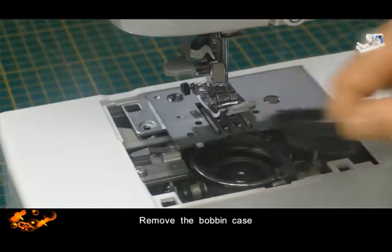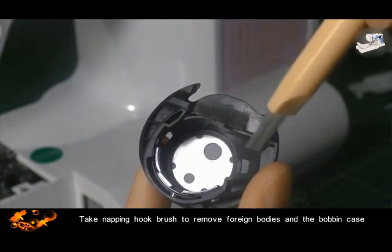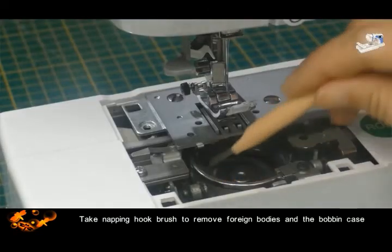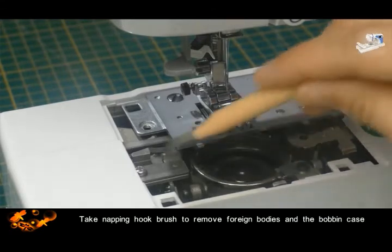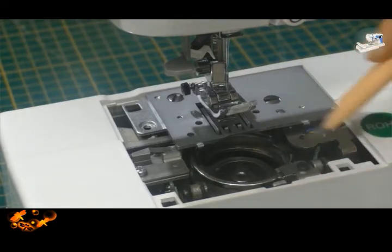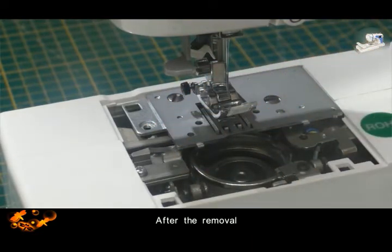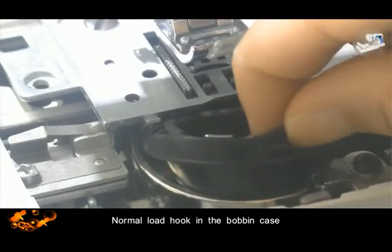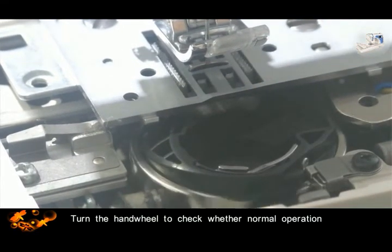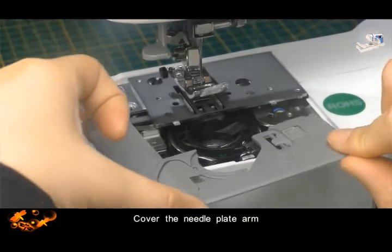Remove the bobbin case. Take the hook brush to remove foreign bodies from the hook and the bobbin case. After the cleaning, load the hook and bobbin case normally. Turn the hand wheel to check whether it operates normally. Cover the needle plate.